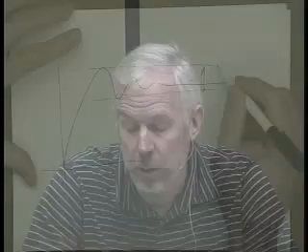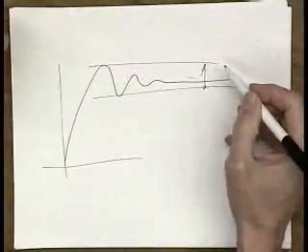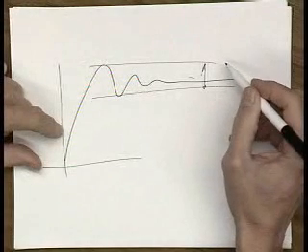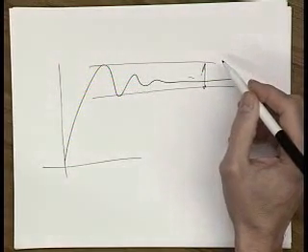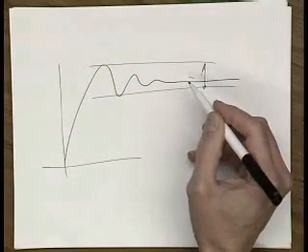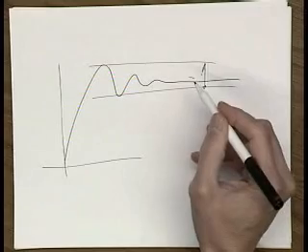In office hours today, we had a couple of interesting issues. One issue came up in the accuracy of SPICE, and we'll post a newsgroup comment on that. When you start asking for very fine results, when you do your settling and the 0.1% error ends up in the tens of microvolts, you need to make sure SPICE is more accurate than that. There's a control for that in one of the parameter files that you need to put in.